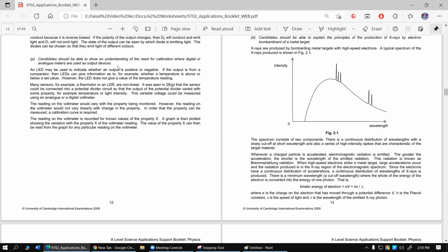So all the crushed ice should be placed in a funnel. We have to fulfill these conditions, which is doable. Not so difficult. But if you're trying to determine the upper fixed point, which is the boiling temperature of pure water under 1 atmospheric pressure, this 1 atmospheric pressure is very important. If you want to achieve that, we have to keep it in steam of exactly 1 atmospheric pressure for a pretty long duration so that the mercury level is at a stable level where it should represent 100 degrees Celsius. Doing this every once in a while can prove to be pretty difficult, but that's how calibration is done for a thermometer.